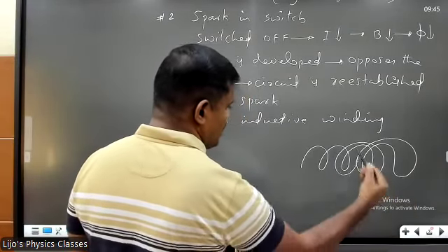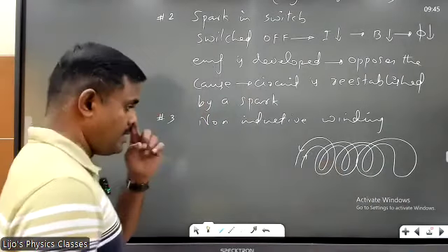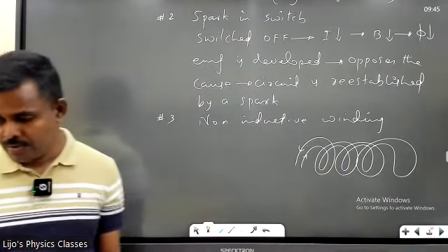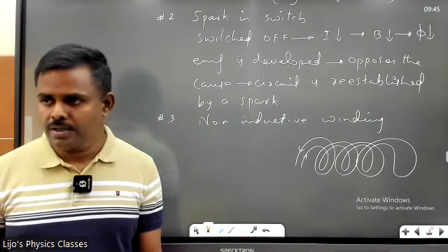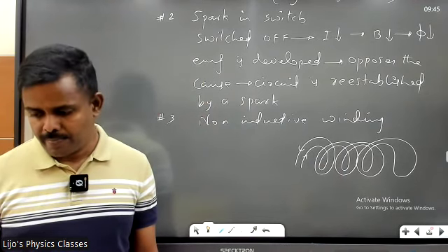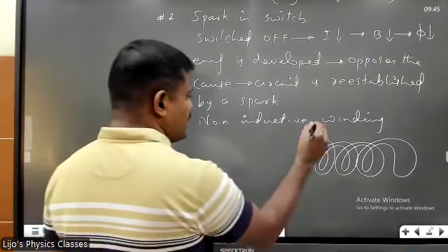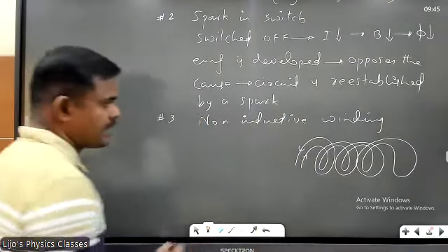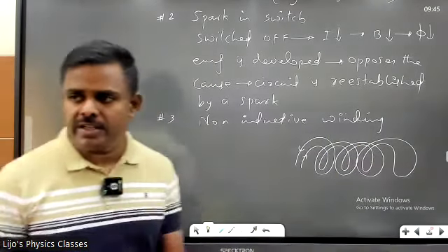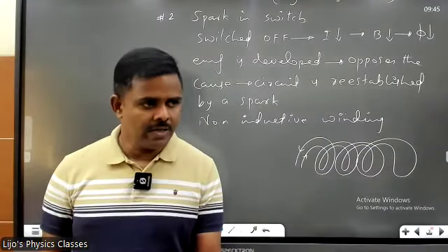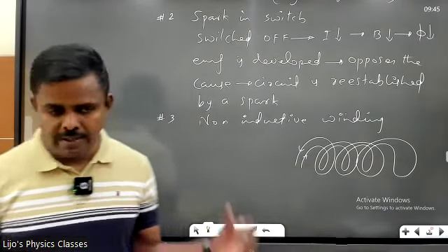A coil wound once, it is wound in the opposite order, right? You're winding it this way, and once you're done, you're winding it backwards. Got it? Non-inductive winding. No induction. Induction is such an undesired effect here. We don't want it, right? What I want is pure resistance, right? Okay. Non-inductive winding, write this.